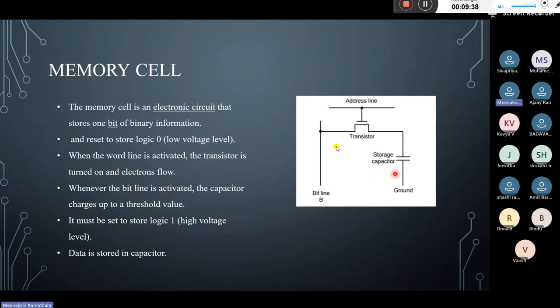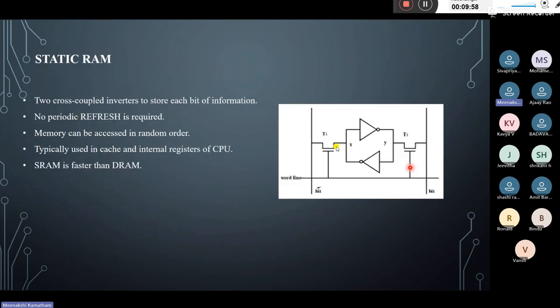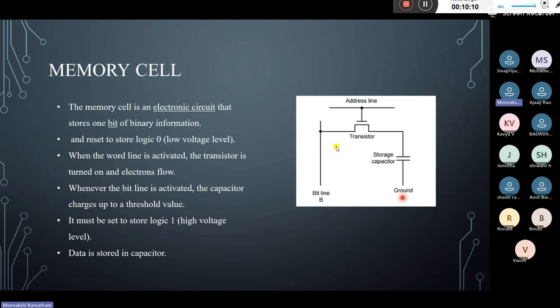After 3 volts, the refresh should occur continuously, which means we are not giving any room for discharging, we are just keeping the data stored. So the refresh command is mainly targeted at the DRAM. In SRAM no refresh is required. No periodic refresh is required there because we are using just transistors and no capacitor. But in DRAM we are using capacitors.